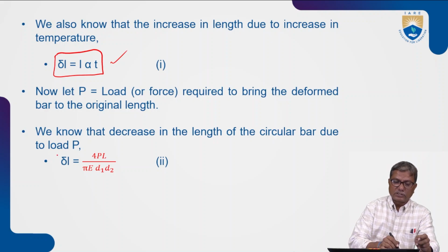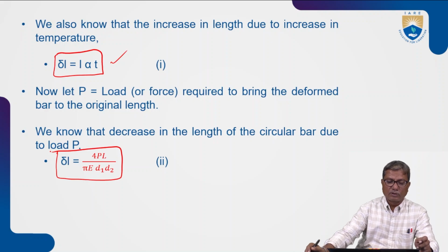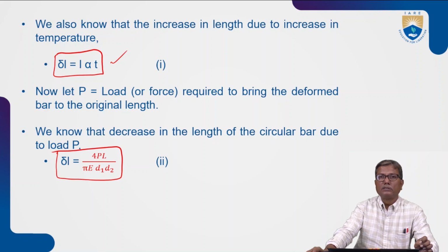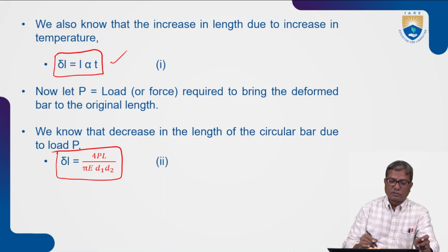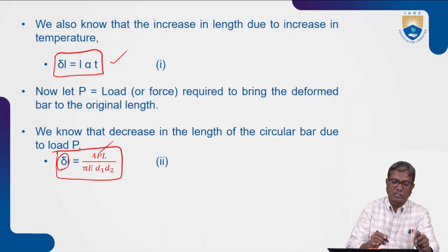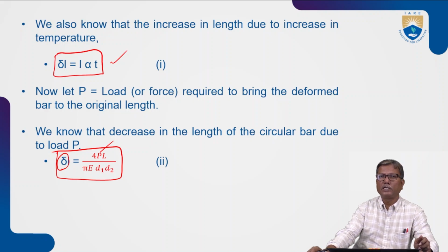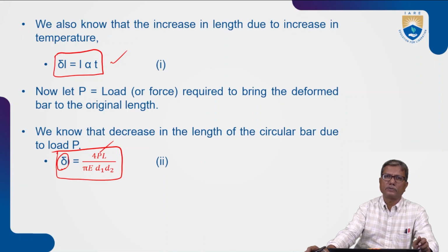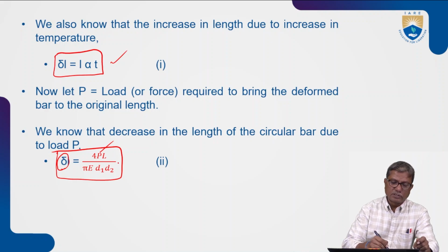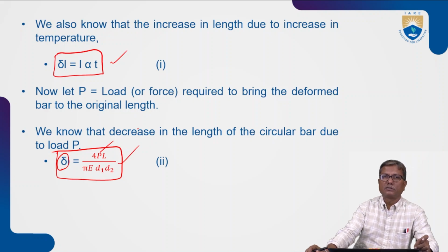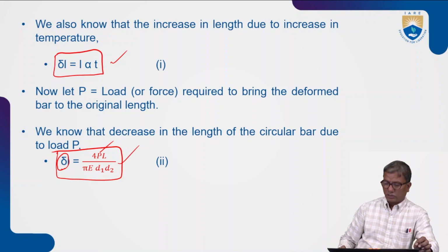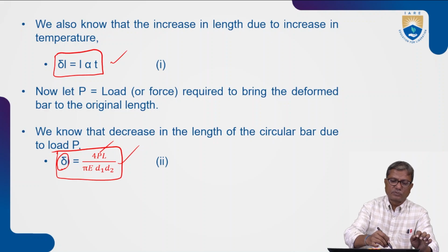And in case of tapering bar, the contraction under the action of force P is given as 4PL by pi E d1 d2. So this is the contraction caused by the force P. So now we can equate these two expressions.